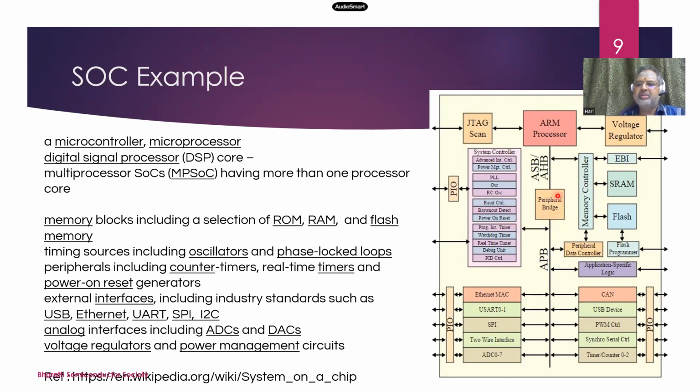So this is a typical example, and this is the backbone of the entire chip. It's called a bus interface. The latest we have are the versions of the AXI bus. AHB and APB are slightly outdated low speed interfaces, so they're not very high performance and don't support high throughput. The AXI interface is a high performance, high speed interface.